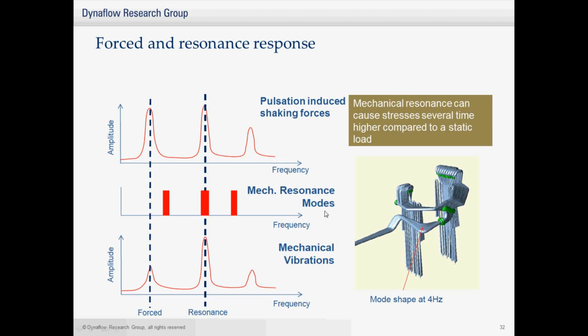And you should definitely take into account that if you would apply the shaking force as a static force, you would get a much lower vibration, and so the mechanical resonance can actually amplify that static force effectively and cause many times larger vibrations.